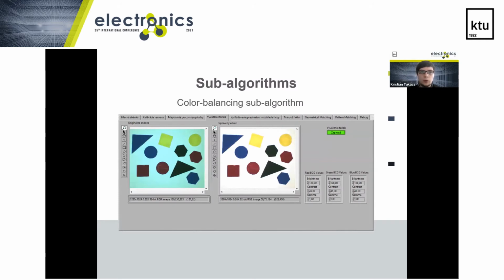Since some algorithms use segmentation based on color information, we must correct the input images to provide a white color balancing. The shift of the color spectrum in the captured image occurs because of the CMOS sensor of the used camera and the LEDs in the light unit emit light in the blue part of the color spectrum. So correction of R, G, and B gains in the camera sensor must be set up